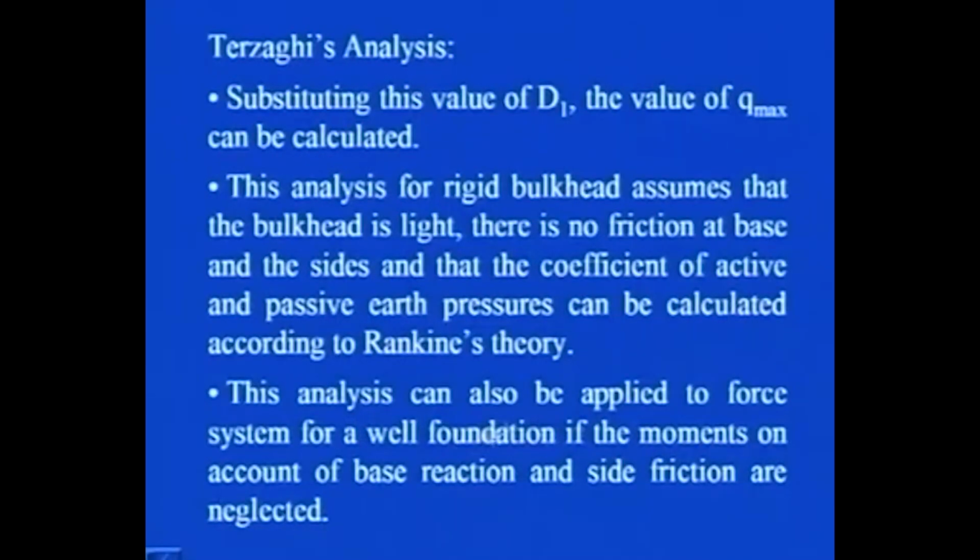Further, this analysis can also be applied to a force system for a well foundation if the moments on account of base reaction and side friction are neglected. Here we had considered the forces due to base reaction and side friction both, but if they are very small or negligible, so that there is nothing to lose as far as the stability of the well foundation is concerned, you can neglect them, and then Terzaghi's analysis can also be used for the same.